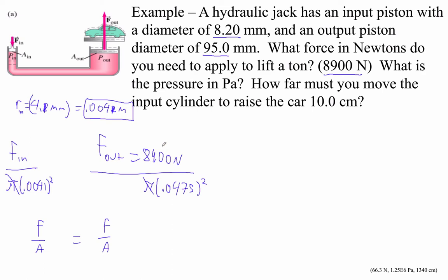All right, so let's see. I'm going to go 8,900 divided by 0.0475 squared times 0.0041 squared. I'm just getting what F is. And I get that the input force is 66.6 newtons.